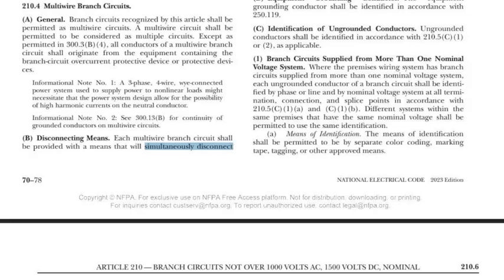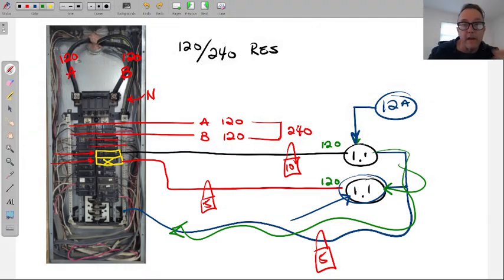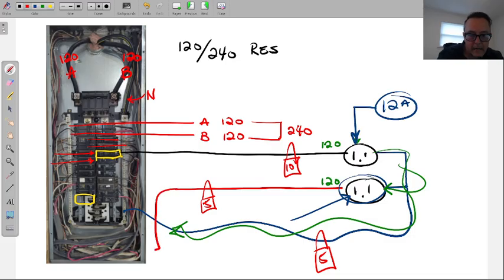So, for example, and this is what happens a lot, this is why you have to be careful. And I think this is where that Instagram video showed up, asking the question. Let's say someone can't put this breaker next to it. There's just no space in the panel. The only other space is down here somewhere. And now I've run this hot, or whoever ran the hot, to this breaker. You don't know that they're sharing the neutrals. You're about to get into this circuit.